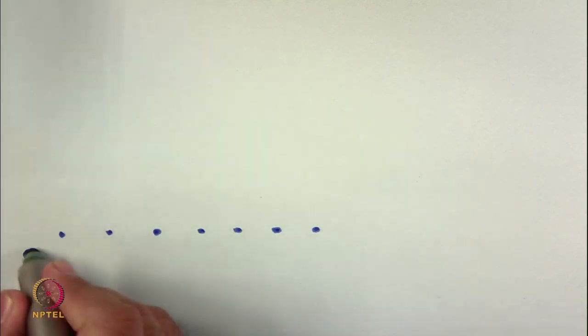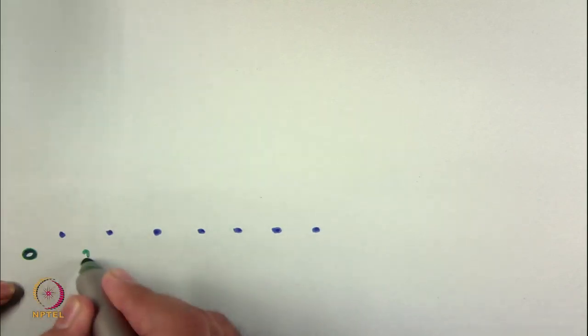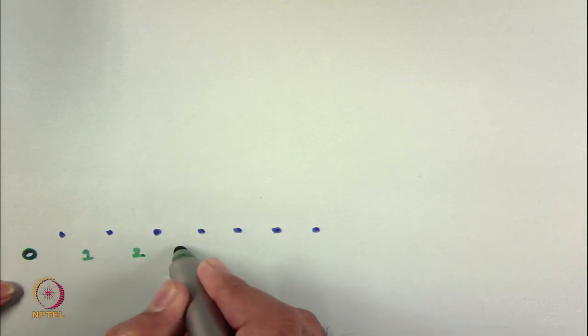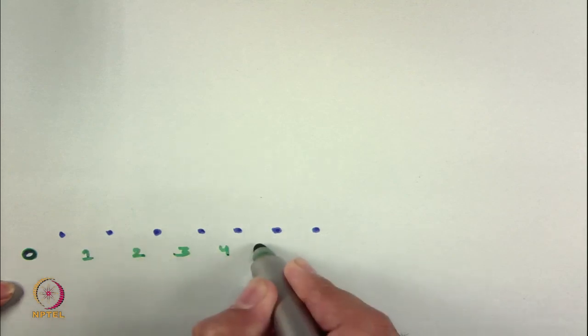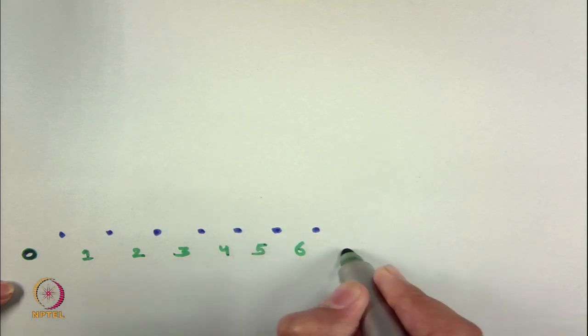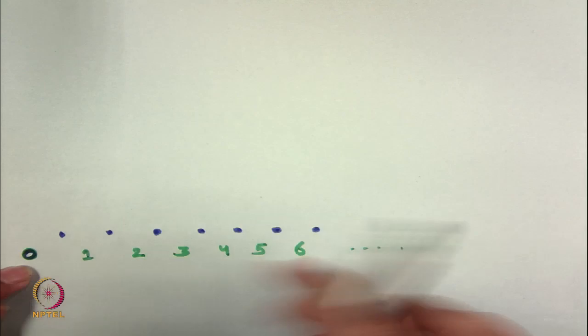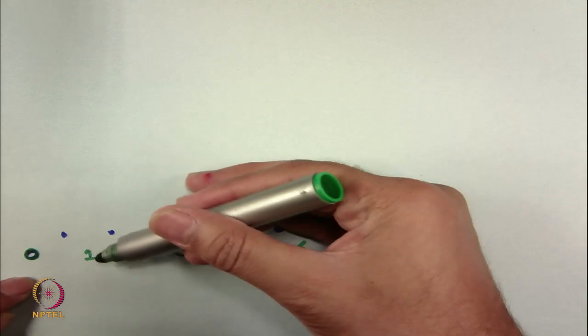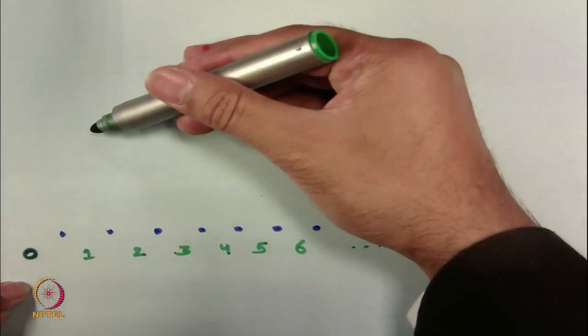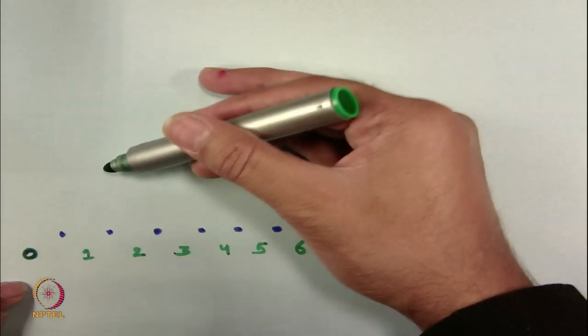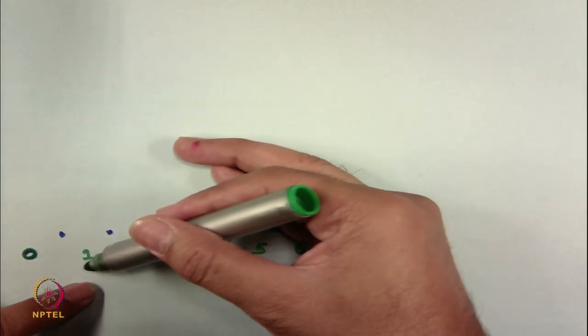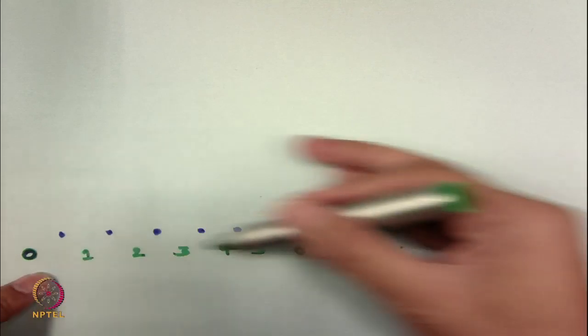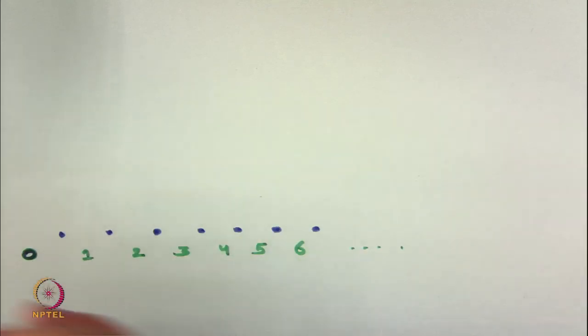Let us suppose this is the 0 position, this is first position, second position, third position, fourth, fifth, sixth position, it depends. And this guide bar position is actually shifted by half pitch. Why is it so? Because the guide bar has to swing across the needle. So, there should be some spacing when the guide is travelling from the back side of the needle to the front side. That is why these positions have to be appropriately defined.